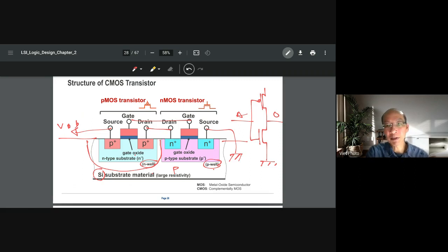And when we have a CMOS transistor like this, I think we have that in the next one, but I can explain from here. Here's the inverter. When the input is 0, this one will turn on, so you have current going out here, you get VDD here, so you get logic one at the output.